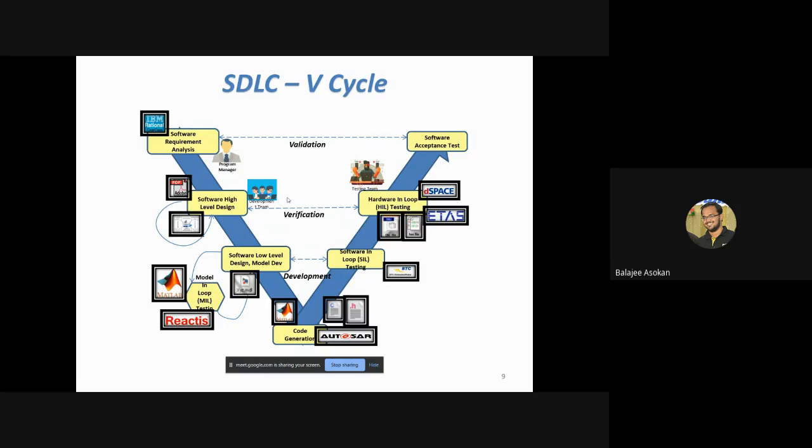These people will take the C code and try to convert it into something like a .hex file or an object file, basically into machine language. Then they will flash it into an ECU, which is the final production ECU. This ECU will be connected to a big hardware rig, which they call MicroAutoBox or a dSPACE device, connected via wires and different harnesses.